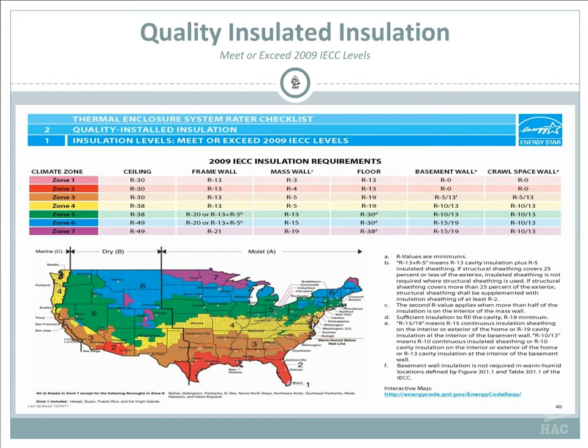It depends on the amount of insulation you're going to want in your ceilings. When you get up into the northern United States, you need an R49. For an R49, that means you have to have some attic space, because even with the high-grade blown-in R5 per inch, you're still looking at about 12 inches of high-density fiberglass that you're going to be blowing in. So you need to allow for that room up in the attic.